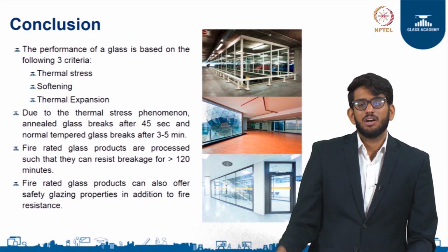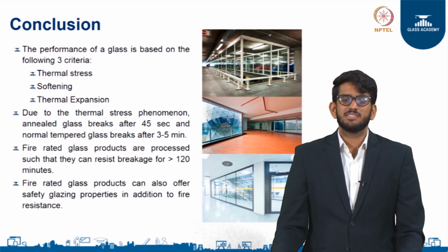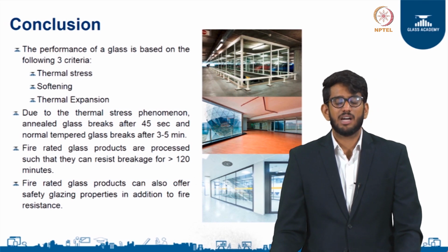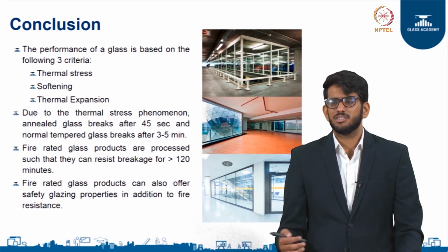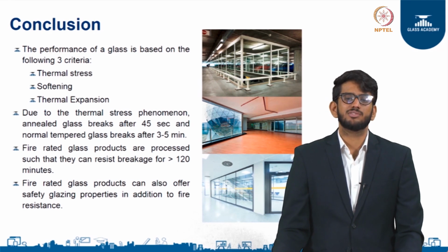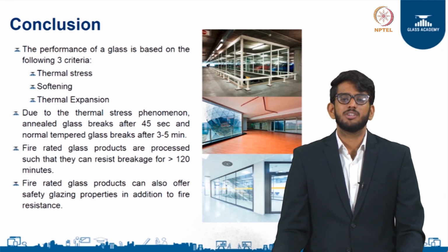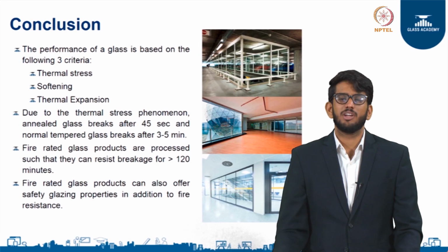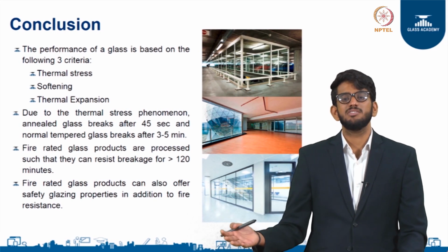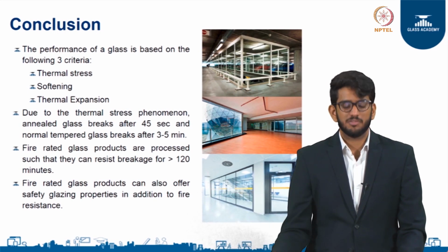Also, if you are looking at fire resistance applications which require fire resistant products, the rating that you generally require is 2 hours or 120 minutes. So, here we are talking about the misuse of glass, which can only withstand 5 minutes of fire, for applications which require up to 2 hours of fire protection.